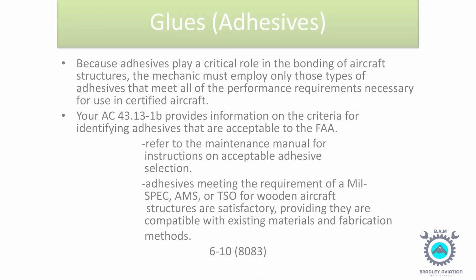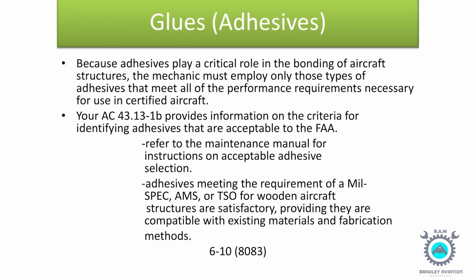6-80. Glues, adhesives. Because adhesives play a critical role in the bonding of aircraft structures, the mechanic must employ only those types of adhesives that meet all of the performance requirements necessary for use in certified aircraft. AC 43.13-1B provides information on the criteria for identifying adhesives that are acceptable to the FAA. Refer to the maintenance manual for instructions on acceptable adhesive selection.